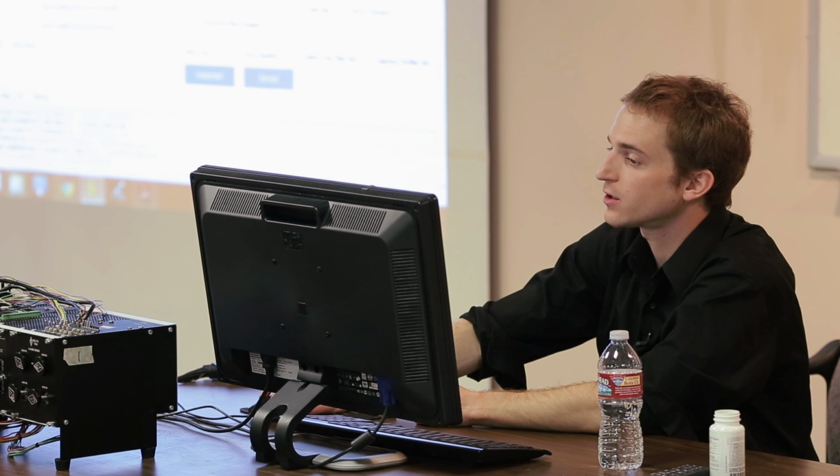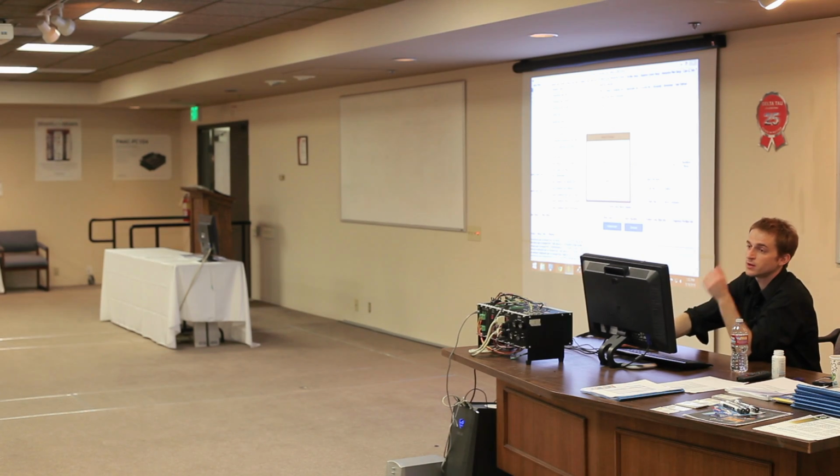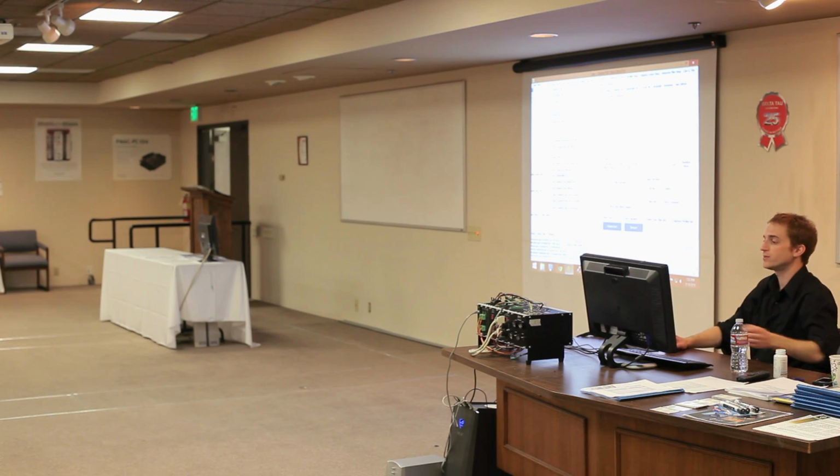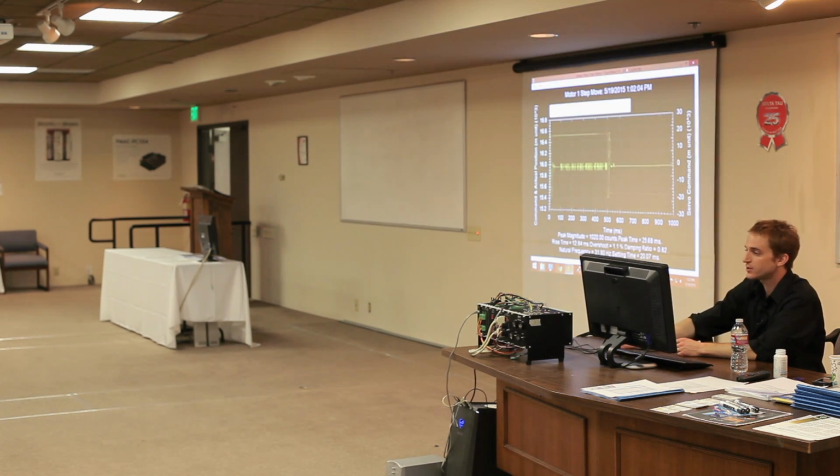A good number to start with is 0.001 in general, because Ki can destabilize the system really quickly. So its magnitudes are generally much smaller than the other gains. And you can see that just adding a teeny bit of Ki has completely eliminated the steady state error on the return very quickly and a little bit more slowly on the rise.